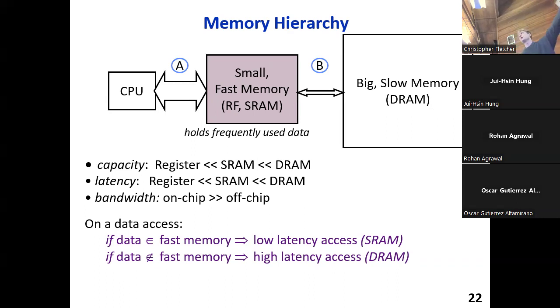So levels in this pyramid that are closer to the CPU are faster to access. This is like registers and potentially small SRAM, but the capacity is commensurately smaller. And as we go out, we get to larger but higher density memories, if we in fact think that we need those higher density memories.